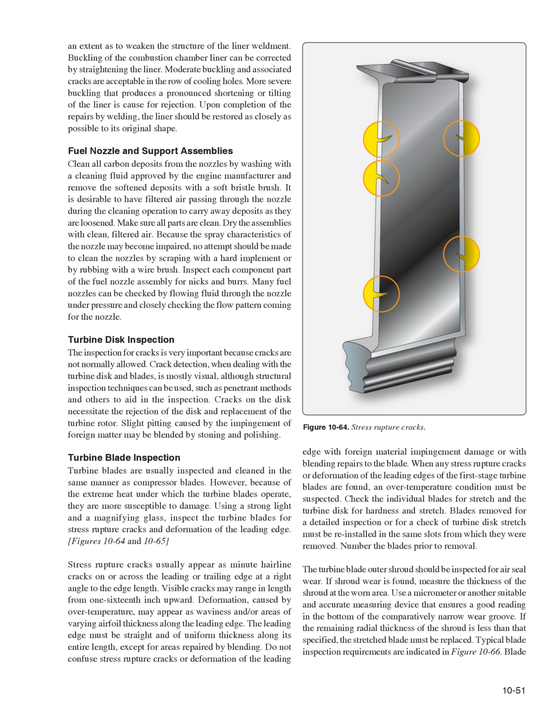Cracks on the disc necessitate the rejection of the disc and replacement of the turbine rotor. Slight pitting caused by the impingement of foreign matter may be blended by stoning and polishing. Turbine blade inspection. Turbine blades are usually inspected and cleaned in the same manner as compressor blades. However, because of the extreme heat under which the turbine blades operate, they are more susceptible to damage.